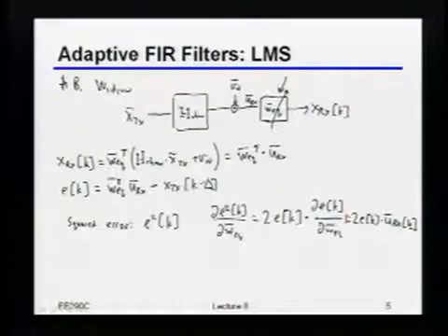In an amplifier, when you want the error to be 0, what do you do? Negative feedback. Yeah, you put it in negative feedback with infinite gain at DC, which means you integrate it, right? So, for those of you who like math, this is just another way of saying that basically you build a loop where you just follow the gradient in terms of what should be the value of the coefficient.